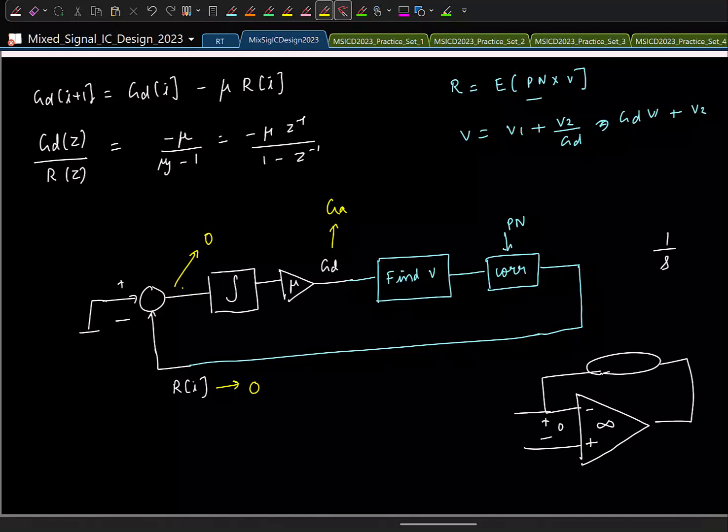The idea is similar, right? You have some quantity, you want to make it equal to some other quantity. So you take the difference between the two, you get an error signal and give that error signal to an integrator and enclose the entire thing in negative feedback. And the negative feedback loop will enforce that the DC at the input of the integrator will be 0. So if the error signal is given as the input to the integrator, the error will go to 0. Okay.